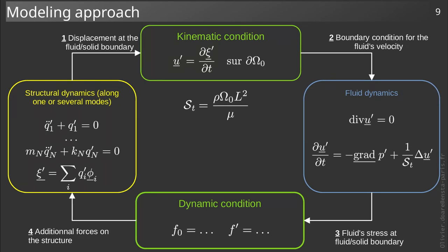We can make a first observation with regard to these equations. In the momentum conservation, the velocity appears with two different orders of time derivative. This has the consequence of introducing a timescale specific to the dynamics of the fluid. This was not the case before, and the fluid responded instantaneously to the solicitation of the solid at any point